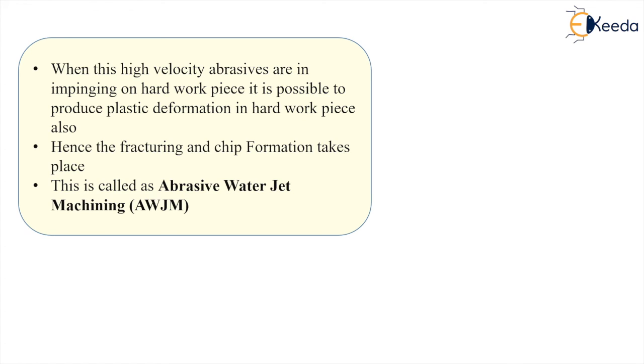At the same time, we learned about water jet machining. Here water is causing plastic deformation and fracturing of the work surface with a high speed water jet, which can be used only for soft materials like rubber. The limitation of water jet machining was that it cannot be used for hard workpiece material. So we added the abrasive grains, so that now it can be used for hard workpiece material also, and the process is now known as abrasive water jet machining.